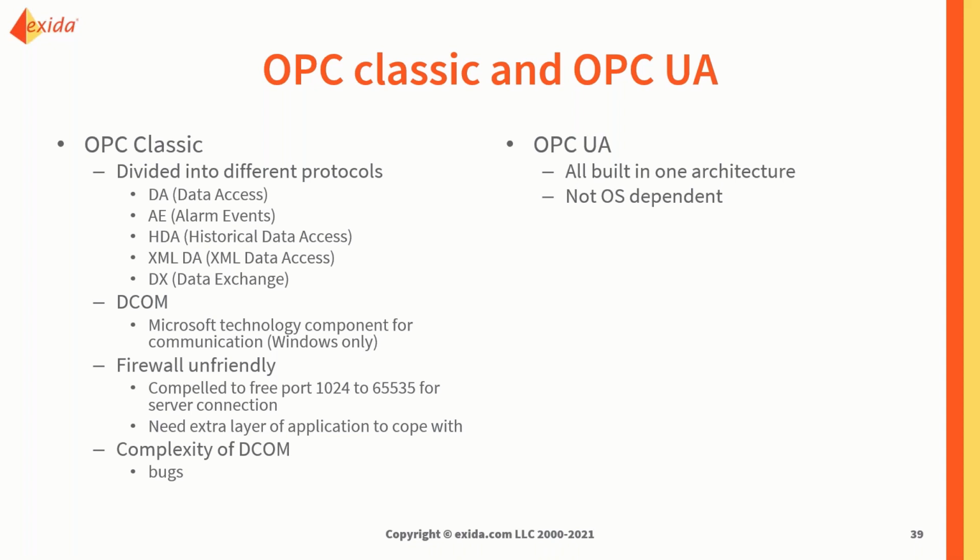You can't really use it on other operating systems, and a lot of operating systems need to run on Linux. That means you can't really use OPC Classic on them. But OPC UA is not OS dependent in that sense, so you can use it across different platforms.